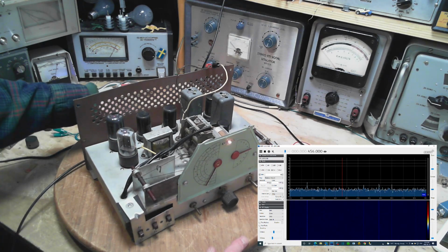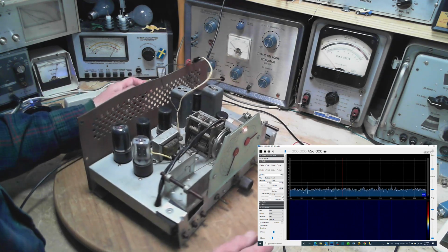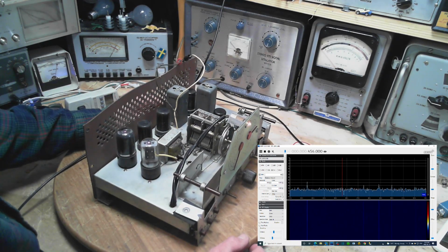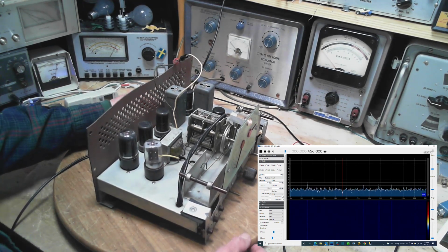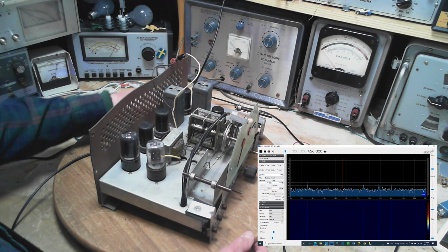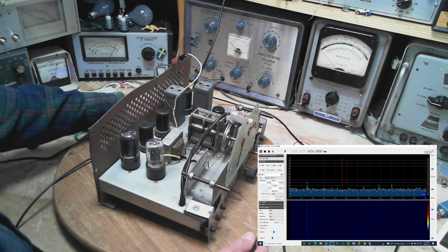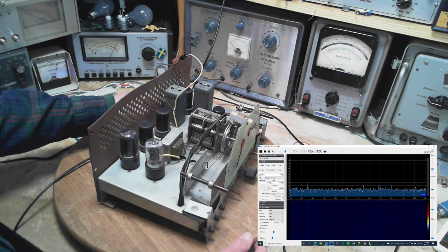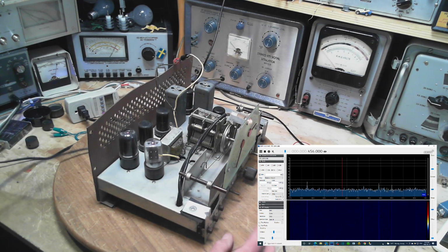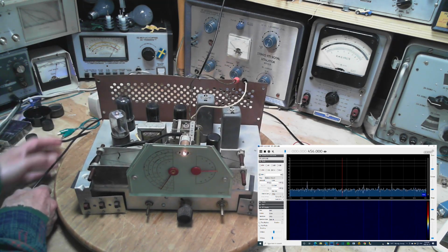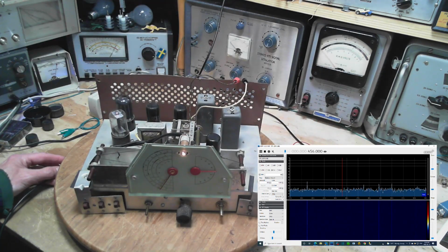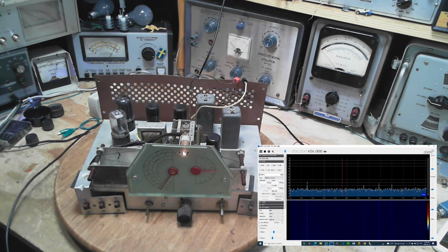Did not have the ground connected during all that. Let me hook up the antenna ground. Why does the radio go so quiet when I hook up the antenna ground? I believe it's because I'm using low impedance antennas, and there's an awfully long coax lead on this antenna I'm using.